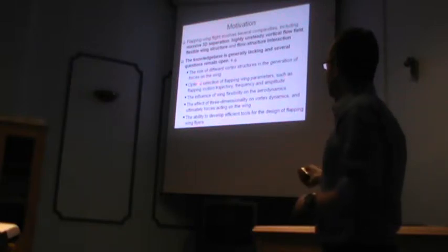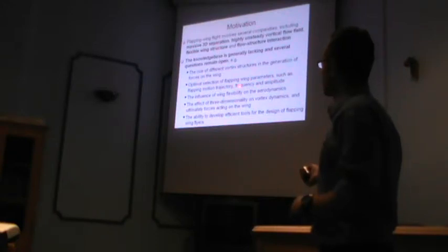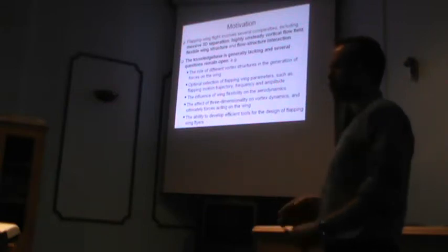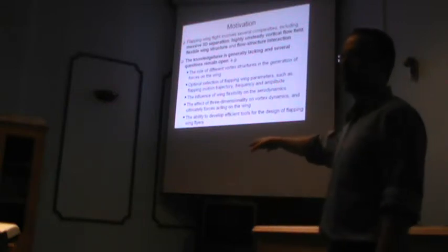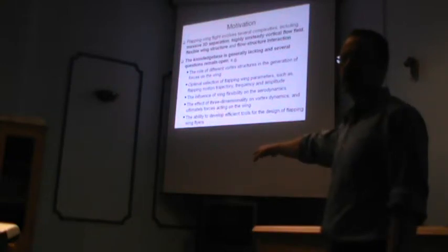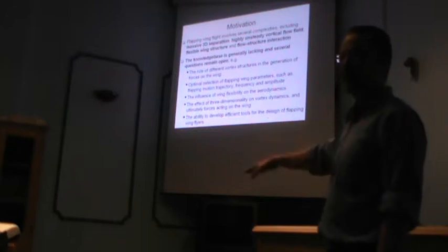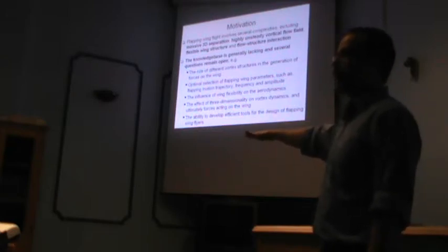Also, imagine you're designing one of these things, so you're going to choose a flapping wing. You will need to choose a frequency for flapping, you'll need to choose an amplitude, you'll need to choose a trajectory. If you want to generate thrust, I will show you in a few slides the basic physical mechanism, how you can actually generate thrust by moving a wing up and down.